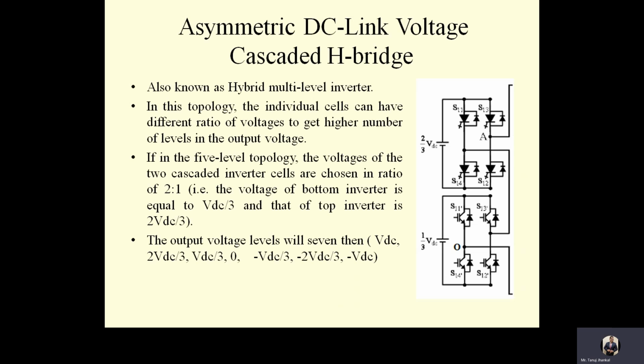Now the advantage of such a multi-level topology is the requirement of a minimal number of devices, as proposed in the literature. It is possible to operate the inverters at different frequencies, and in the extreme case, the top inverter can switch at the fundamental frequency and the bottom inverter can be switched at the PWM switching frequency, to improve the overall efficiency of the drive.